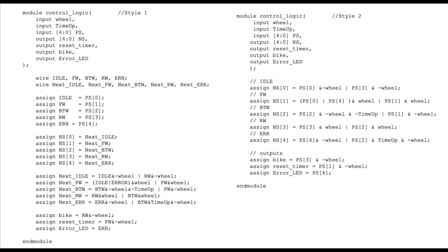And one of the things that happens is you need to change your code, and if you're changing something 16 times, it slows you down quite a bit. So I highly recommend that you use buses when you can, and buses of flip-flops rather than individual ones.